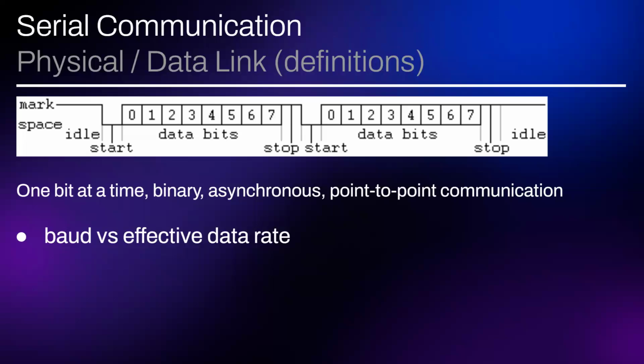So when you're sending data, this has 8 bits here, but we're actually sending 10 bits in order to send those 8 bits. So you're not getting the full bandwidth, but the baud rate is the signaling rate, how many of these you can send in a second, essentially. So a common baud rate for serial links is 115,200, 115.2. I think that's about 8 microseconds. Yeah, it's a little more than 8 microseconds. 8 point something.